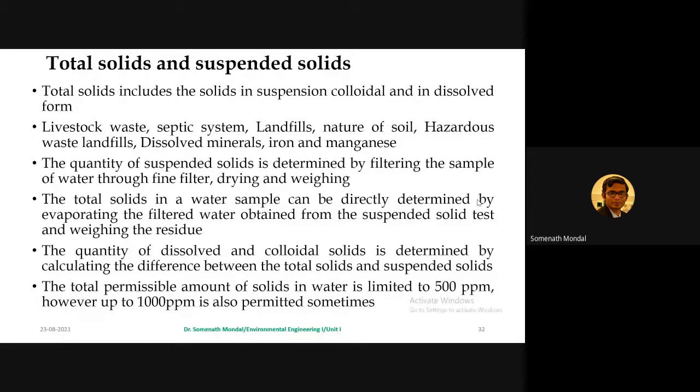So you will get the parameters total solids and suspended solids, as well as colloidal solids. The total solids in a water sample can be directly determined by evaporating the filtered water obtained from the suspended solids test and weighing the residue.